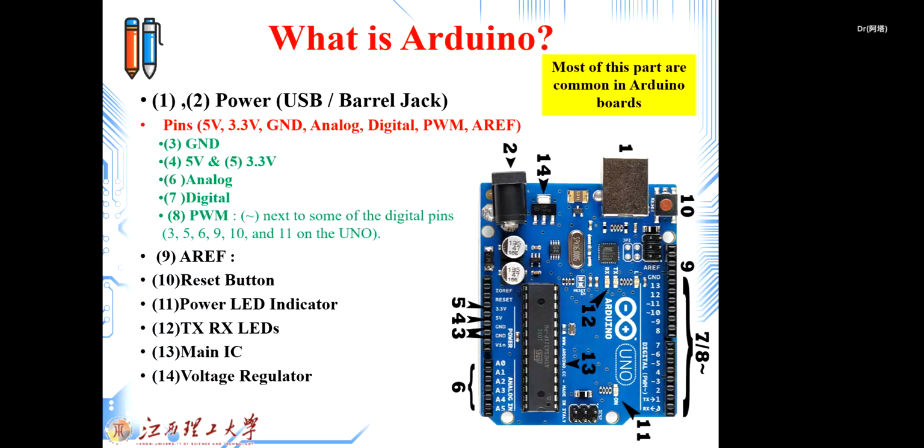And one fixed feature for all Arduino boards is that you have one small LED which is connected to pin number 13, and there is no need to add any external LED to check pin number 13. Why did they put this? Because regularly, when programmers want to be sure that the program loaded properly or not, they use one LED and just make it blink. Like this, they preset the LED inside.